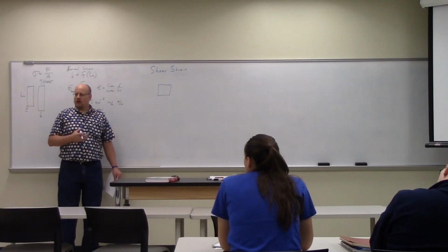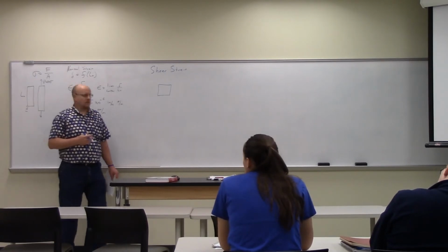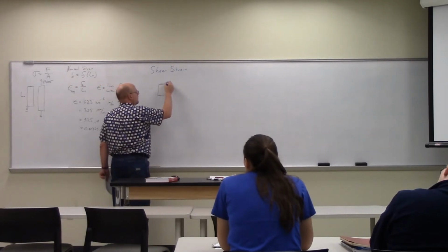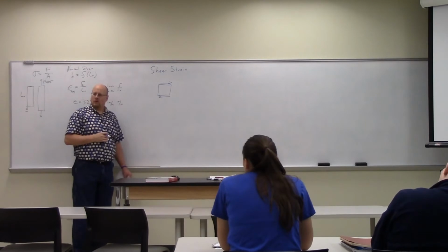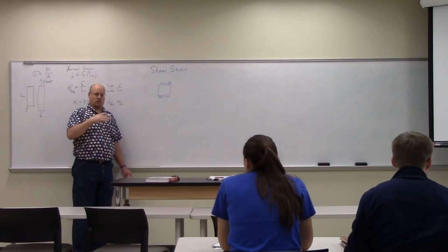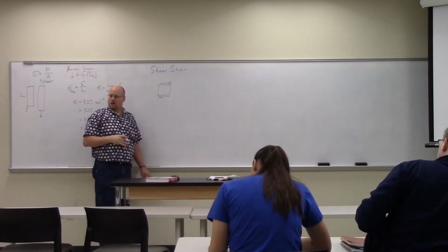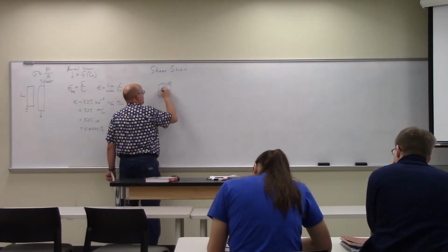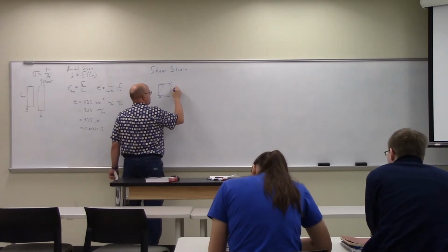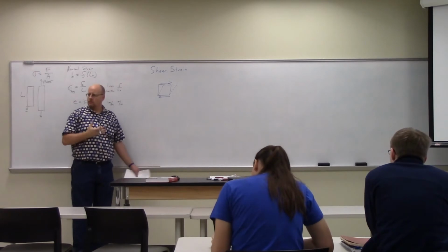It doesn't count unless you say it out loud. Two forces in opposing directions on each side? So you're saying this? Yeah. Right, so that would be a shear stress. Shear stress is a stress on the top surface that's not orthogonal, that's in the plane of the top surface. And as a result, it will deform something like that. Does that make sense?